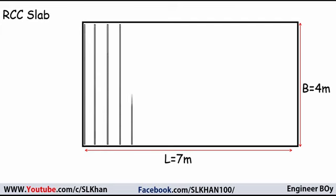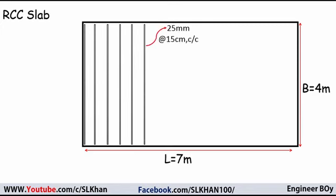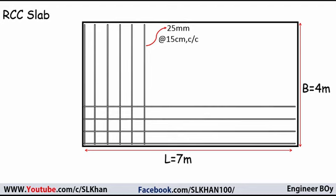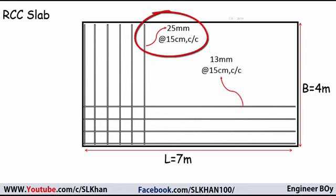Here we have a slab with length equal to 7 meters and breadth equal to 4 meters. There are main bars and temperature bars. As you can see in the drawing, the main bars are 25 mm at the rate of 15 centimeter center to center. Here 25 mm is the diameter of the bar, and 15 centimeter center to center means just the distance between two main bars.